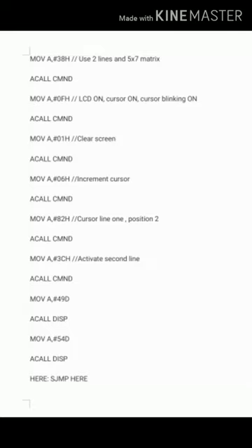Then you also send 01H, because if any data is already being displayed previously, it will not look nice. You simply erase the screen. To erase the screen, you should send 01H to the LCD panel. So 01H also you send as one of the commands.